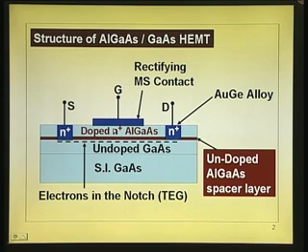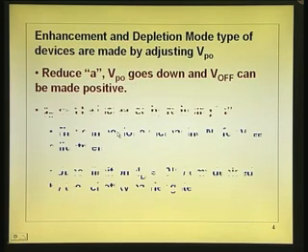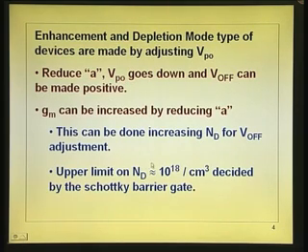If you go to doping concentration 10^19, you will not have a Schottky barrier. You will have a bad Schottky barrier, leaky diode, and close to ohmic contact. So, the upper limit comes from the doping concentration there. You are stuck with that, and stuck with a certain layer thickness. So, Gm has an upper limit because of that. But of course, you can always play with the velocity overshoot effect, very short channel lengths and very high fields to get high velocities, better transconductance.